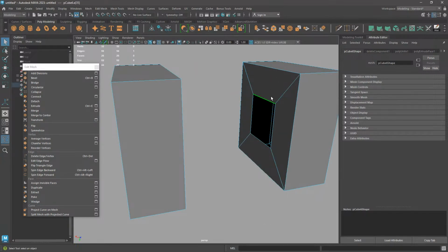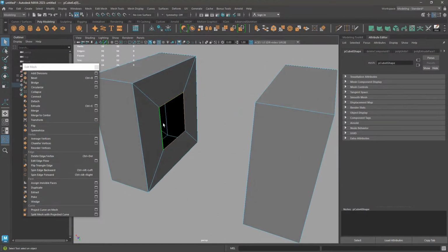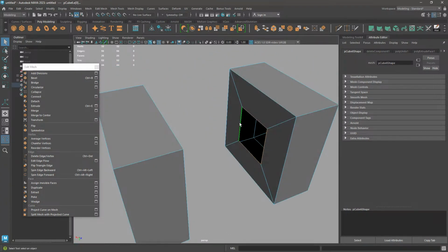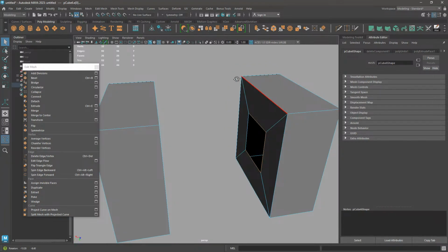First of all, delete that one, double click it. Make sure you select 4 of them on this side and 4 of them on this side. If one side has only 3 edges, this won't work. It says Maya cannot process the selected edges because the mesh being bridged must be combined into a single mesh, or the number of selected edges are not the same, stuff like that. Not the same for the origin and target.